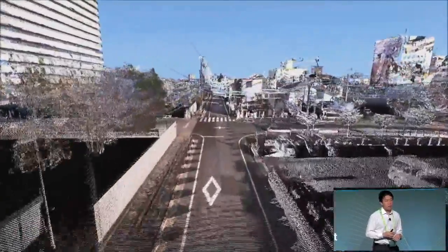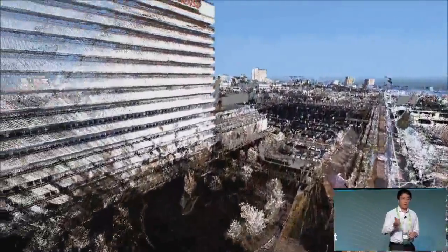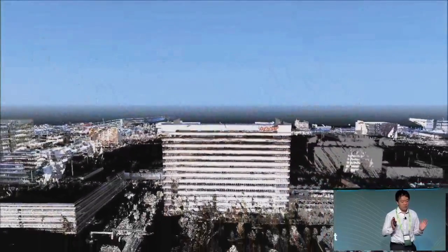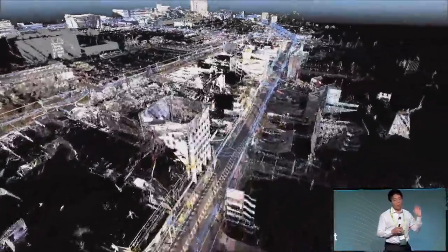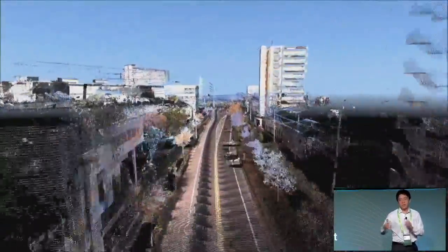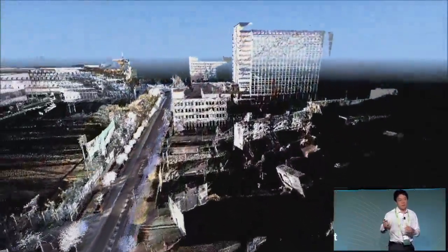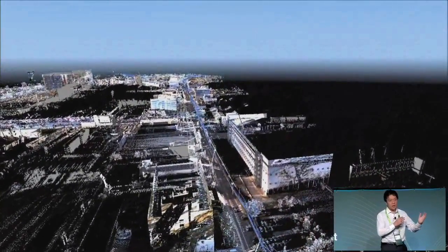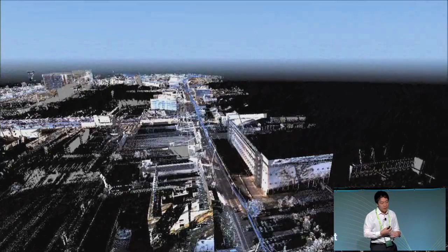Okay, so let me introduce how Autoware technically works. Before you run Autoware, we need a particular data set which is called a 3D map. For a 3D map, you have to run a special vehicle instrumented with some expensive sensors, and once you run that sensing car, you get scanned data of the place where you want to provide autonomous car services. This is not a movie. This is a collection of 3D points, which is often called a point cloud. It's a collection of XYZ points with RGB information. Having this, you can understand what the structure of the place where you operate your vehicle looks like.